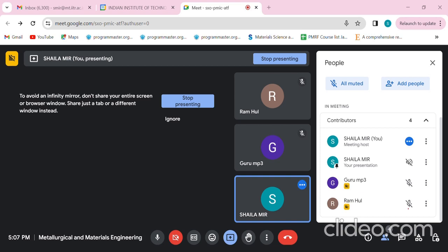The formula I'll write here: F is equal to C minus P plus 1. Because we are concerned with metallurgical processes that are carried out at constant pressure, one of the variables is fixed, so we are only talking about one, that is temperature, so 1. You have to see what the degree of freedom is. This is given, this is 3. You are given a 3 component system, so the component number is also given, and the number of phases you have to calculate.